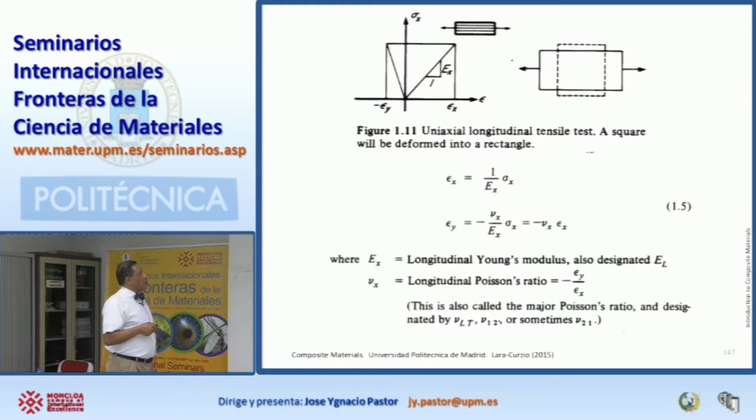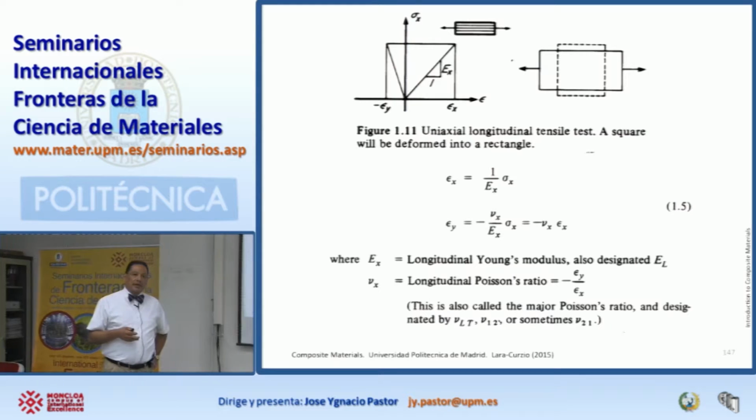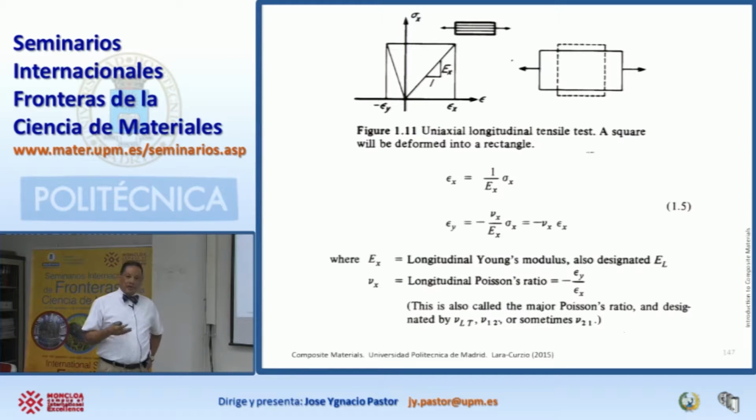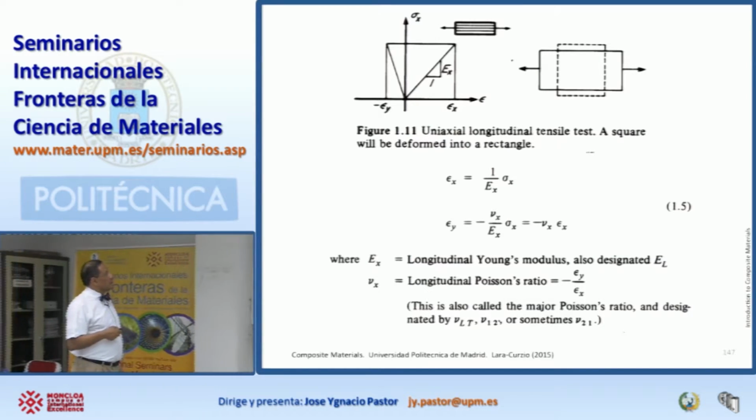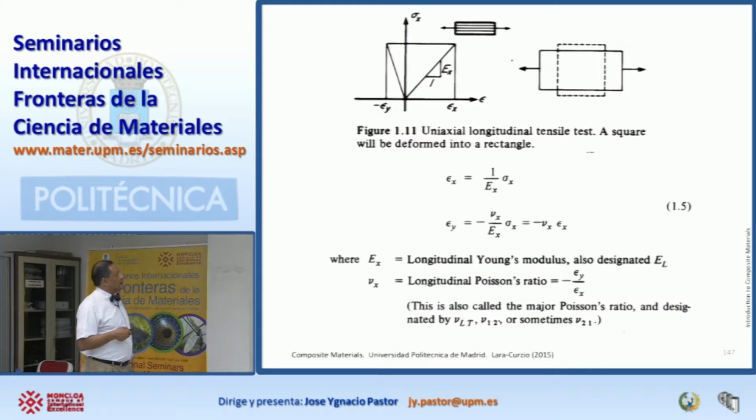And the reason why we don't do that is that doing plastic analysis is very complex. And once you have plasticity, you have damage, and that damage can accumulate. So you are never going to design an airplane where you're going to have damage accumulation in each cycle, because the life is going to depend on the history. So all the design for this structure is going to be based on elastic limits.